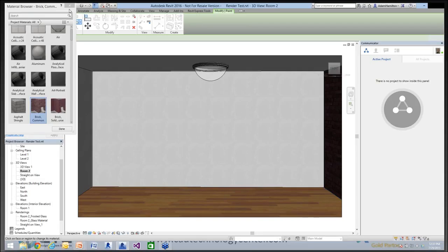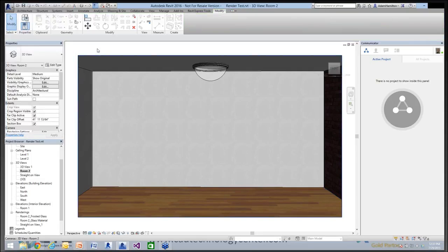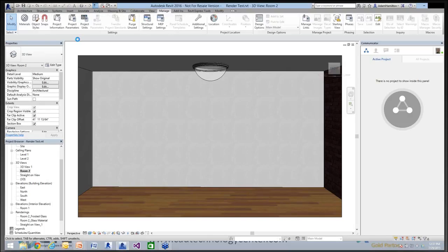One of the things I was asked, and forgive me, I don't fully know the answer because there are some technicalities, is the compatibility between Revit, 3ds Max, and AutoCAD as far as material libraries. Revit utilizes a shared material library inside this material dialog box down at the lower left.